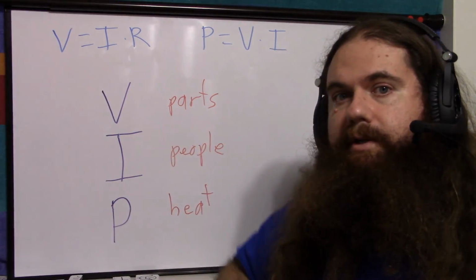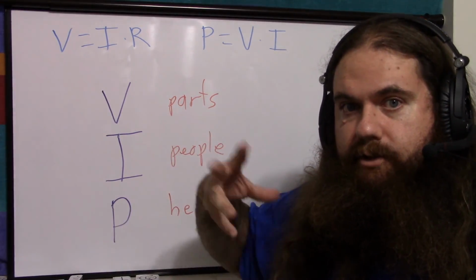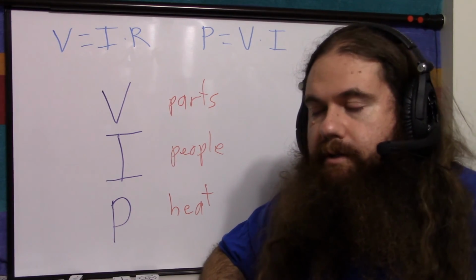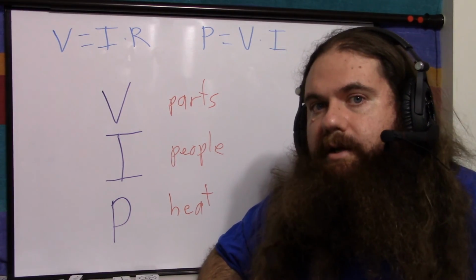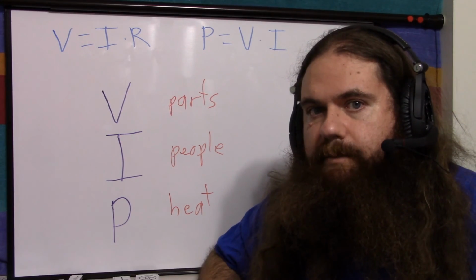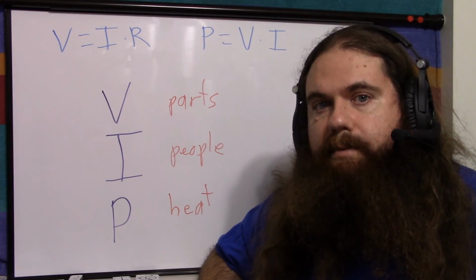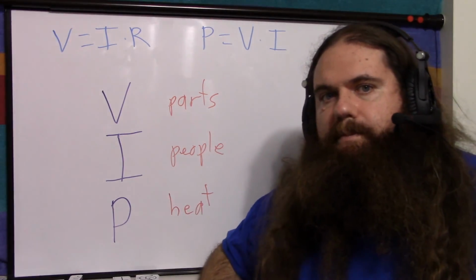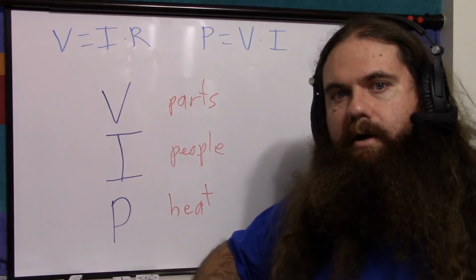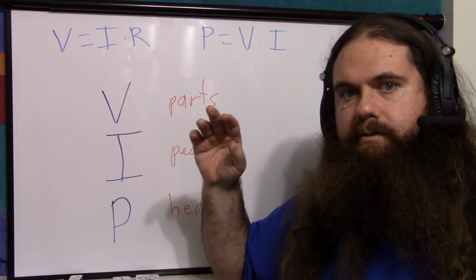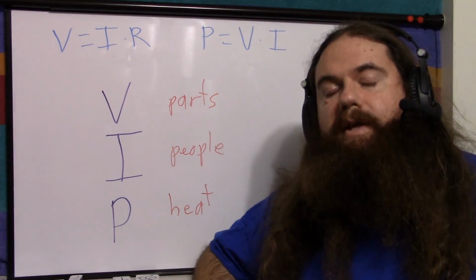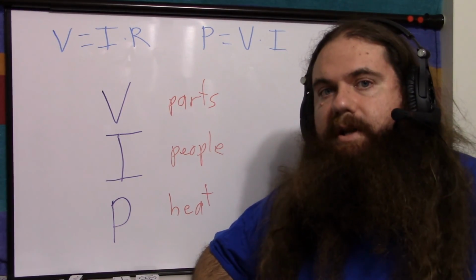Whatever voltage we put in there, we had better be sure: start low, turn it up until we get the operation we want. But we don't want to introduce just any voltage, even if we drastically limit the current, because high voltages can break parts. Current is dangerous to people. If you look at a chart of how much electricity is lethal, there's like a little vertical chart I've seen, they list it in terms of current and voltage is not mentioned.